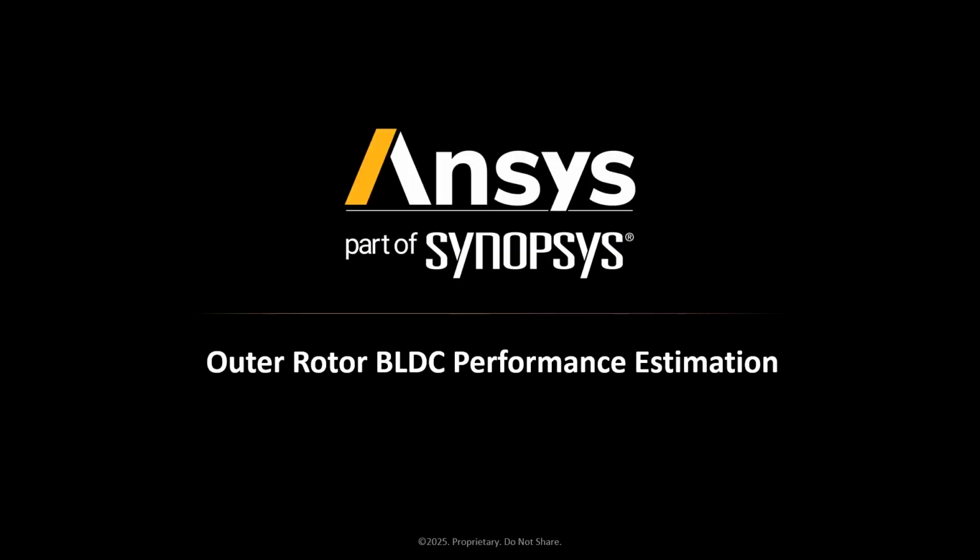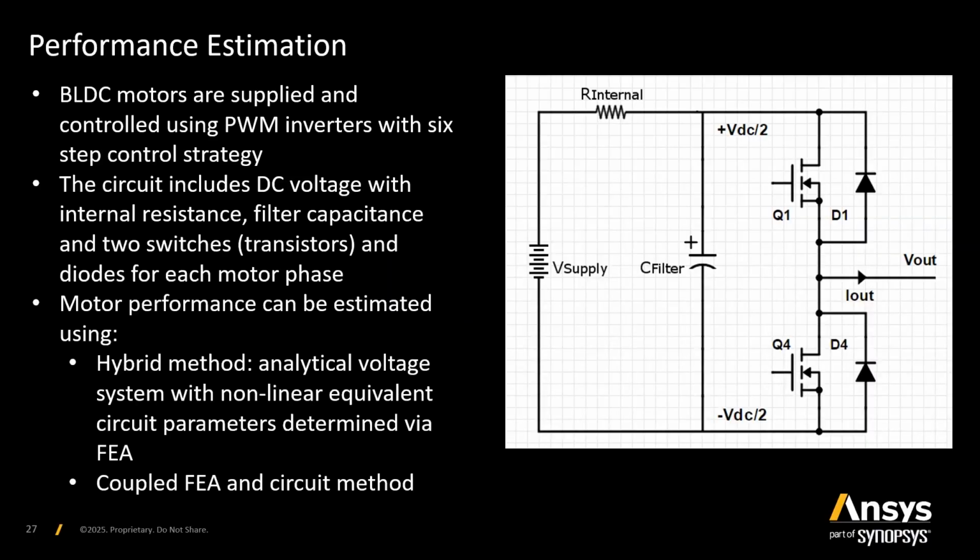And let's see how we model the performance of these machines. In MotorCAD, we make use of this hard-coded electronic circuit. You notice there are two switches and two diodes for each phase leg. We have as well internal resistance for the battery and a capacitance filter.